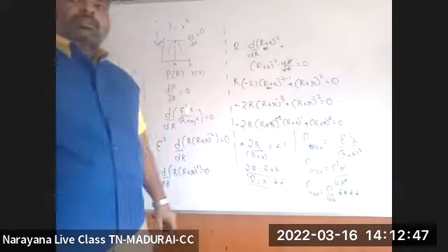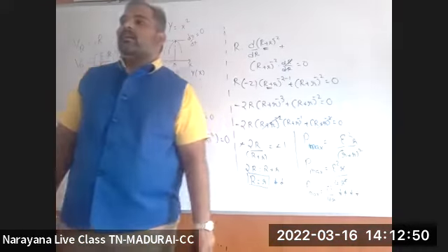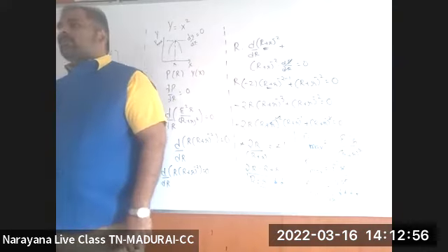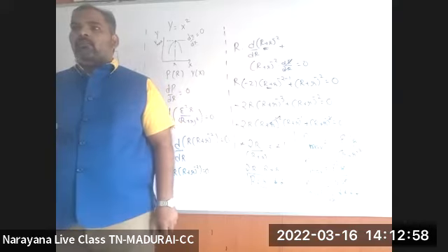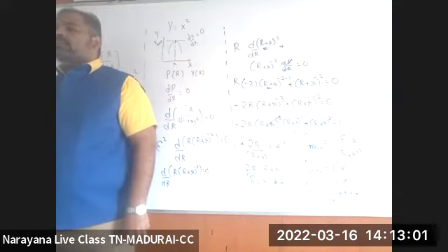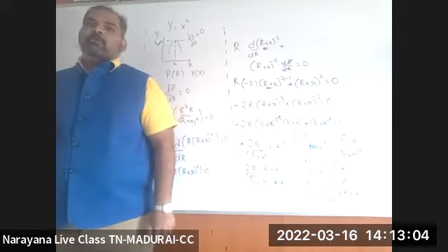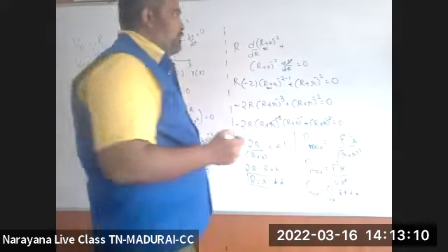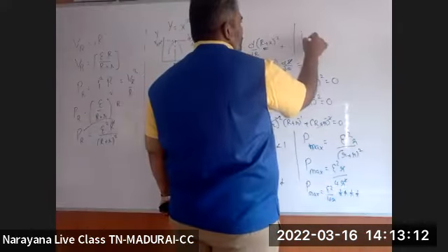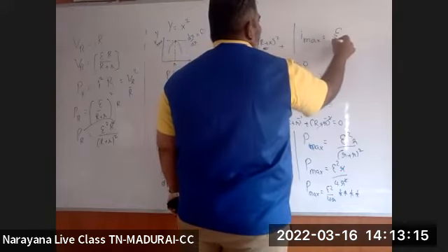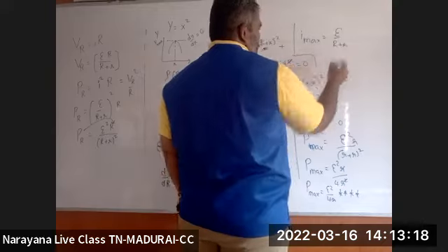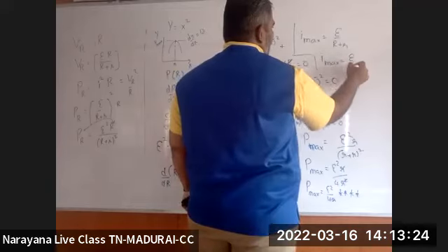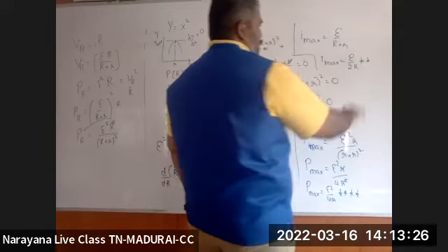Okay. So this is the one I am putting star marks on, compulsory hereafter. To save your time in your exam hall, you compulsorily have to memorize it and find the maximum current flowing in the circuit also. For maximum power dissipation, maximum current should flow. What should the maximum current be? E divided by (R plus r). So put the value of R as r. So the maximum current will be E by 2 into R, or 2 into r.